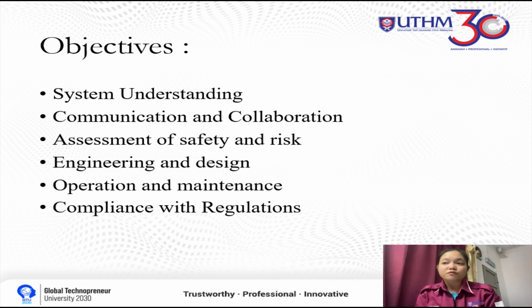P&IDs are also useful for building emergency response plans, identifying crucial control points, and performing risk assessments. And the fourth one is engineering and design. P&IDs serve as the basis for a project's engineering and design stages. They provide the data required for choosing control techniques, defining instruments, deciding on pipe routing, and sizing equipment.